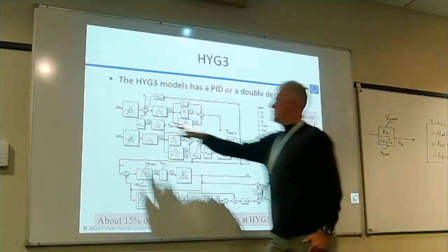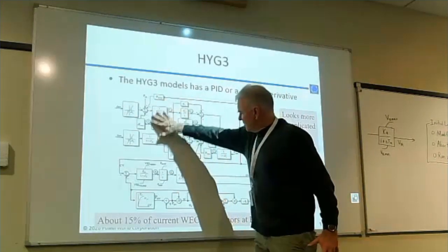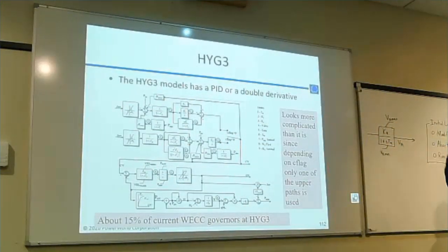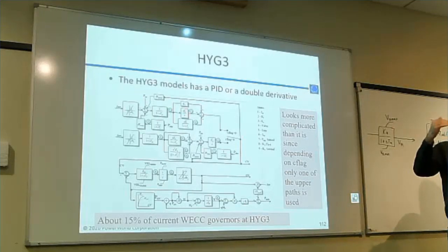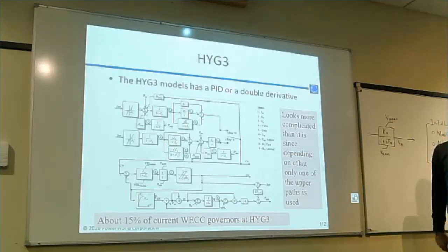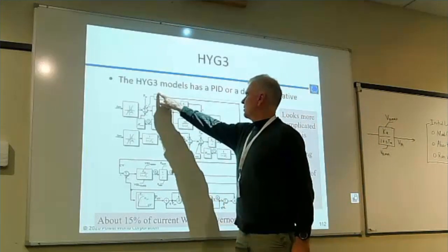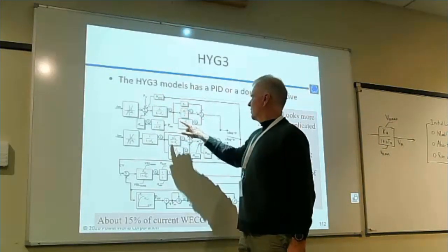Then it brings in the delta omega, then this models the response of the plant itself. And the plant, of course, all you've got on a governor is you're changing how much the gate is open or closed. So is that first block past the delta omega, is that the droop function that's being implemented? This one here, no, I meant back. Well, where is the droop?